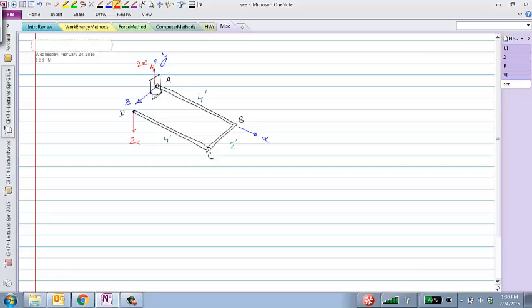Let me see if I was creating that way. So I'd have to rotate it with the right hand rule the other way to keep it in equilibrium. So the reaction moment at A would be in this direction, with a magnitude of 4 kip feet. Okay, so that's the first thing. I hope you are convinced that there won't be any bending moment at that point.